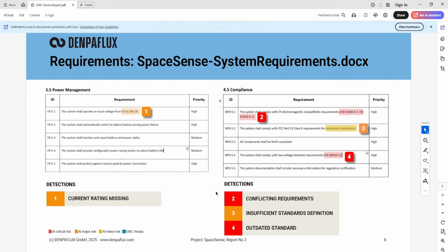As you develop your product specification document, it's always a good idea to list the corresponding EMC requirement, if it exists, for each item in that product specification. These items could include layout and routing, PCB stack-up design, layout and placement of specific circuits, as well as power and grounding strategy. Once you've completed your EMC design review, what's the best way to communicate the results to your project stakeholders? Well, take a look at the example report that we have on screen.